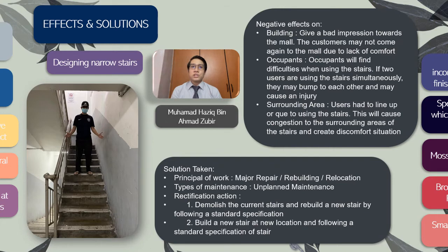For the solutions, principle of work, major repair, rebuilding or relocation. Type of maintenance, unplanned maintenance. Rectification action, there are two actions that can be taken. The first one is to demolish the stairs and rebuild new stairs following the standard specification for stairs. The second option, build new stairs at a new location and make sure to follow the standard specification of stairs.